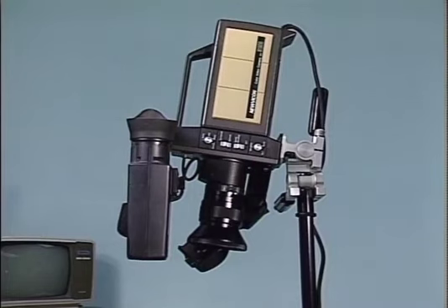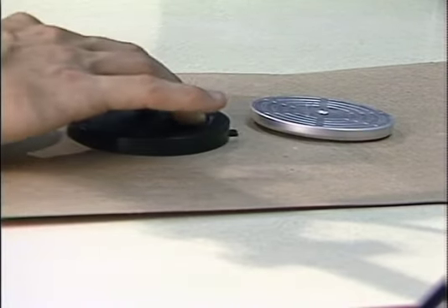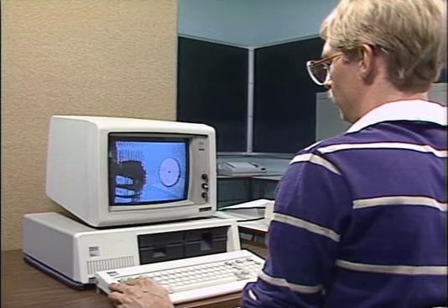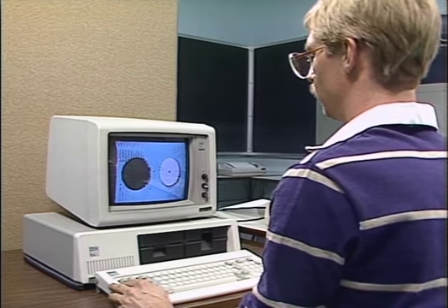The first step in computer vision involves the capture of light intensity and color information in the environment. This is accomplished with a video camera. A scanning electron beam falling on a photosensitive surface generates an analog signal. This signal is then sampled and digitized into a number of discrete levels depending on the resolution of the system. Light intensity thresholds control the range and sensitivity of the digitized image. By adjusting the thresholds, we may filter the image captured and eliminate noise, facilitating further processing toward recognition.